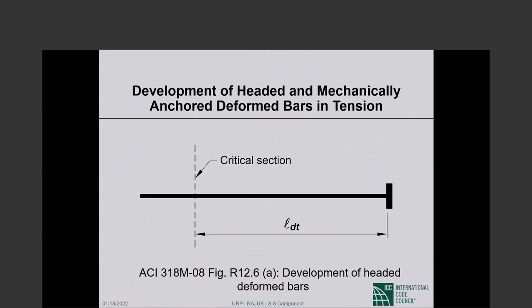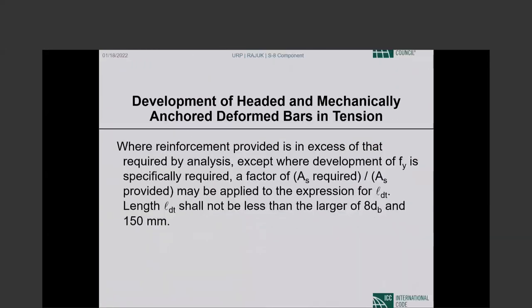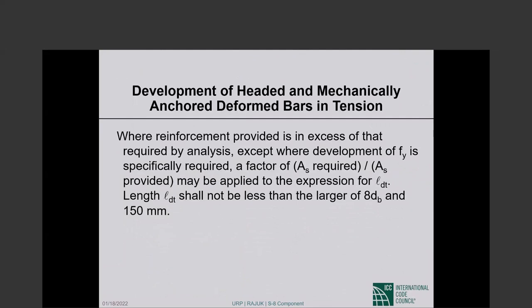So this is L sub dt, from the bearing face of the head to where the bar is fully developed. L sub dt is the headed bar development length.